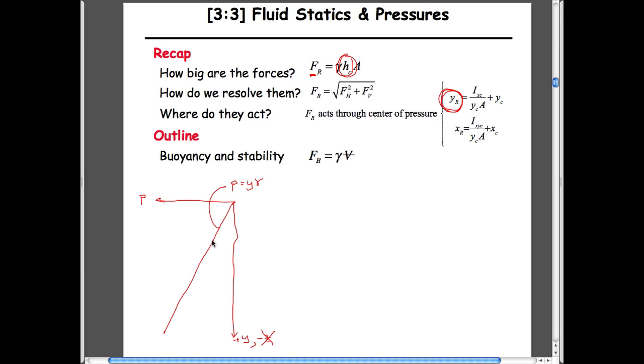And so the point that we've made is that to be able to calculate the fluid pressure on a structure that is applied over some height, then we can calculate the magnitude of the force from calculating h sub c, which is equal to a half of h in this particular case.